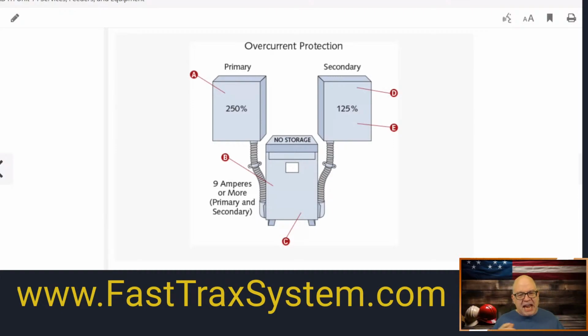So I've got 90 amps here, and I can do the protection up to 250%. So that 90.21 times 2.50 is 225.5 amps. So I'm going to put a 225 amp protection on the primary. I'm going to make sure that that protects these conductors.